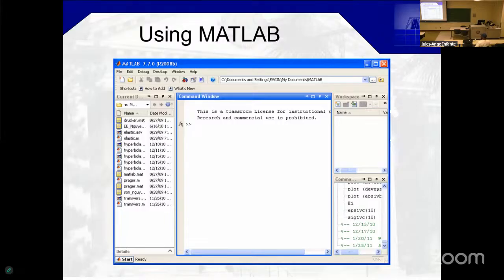That one I probably just copied from somewhere, but I would have to read. This is from the shear. Yeah, it's if you were to solve the matrix. The matrix was subtracting sigma one, yes. The same way we found sigma one, you do this, but instead of being the sigma matrix, it is the S matrix, the deviatoric matrix.